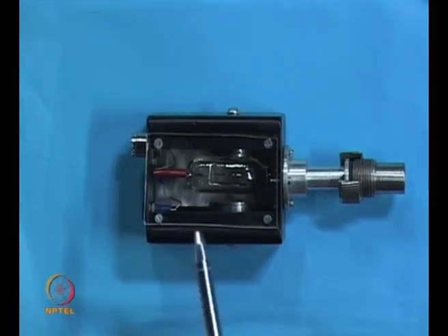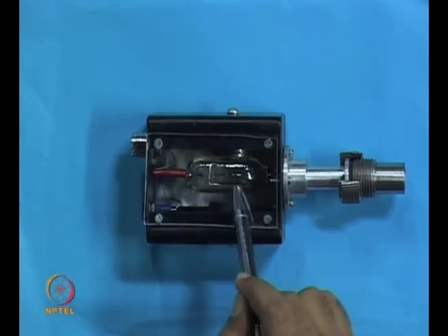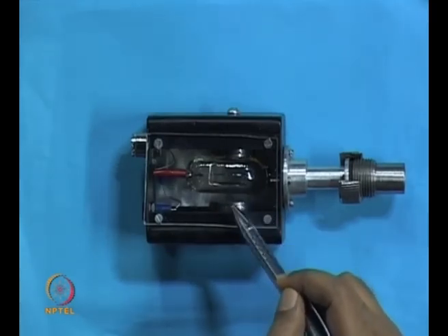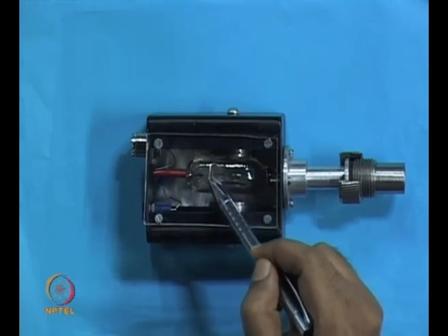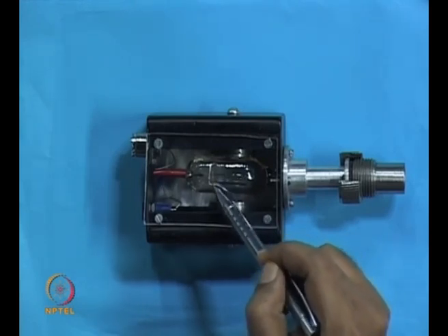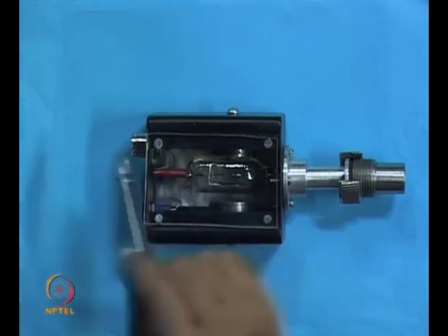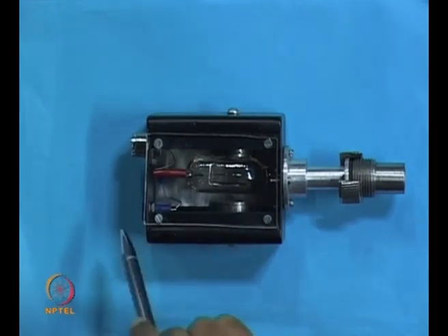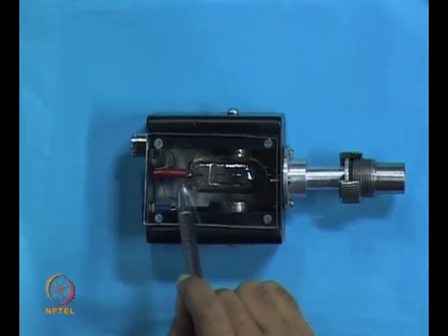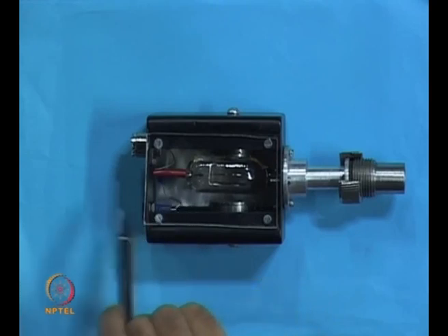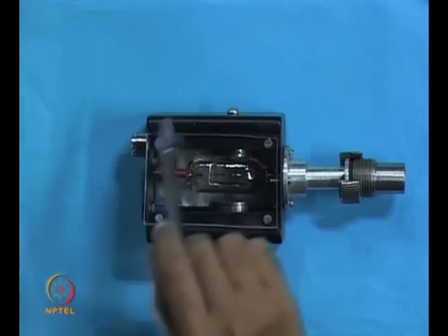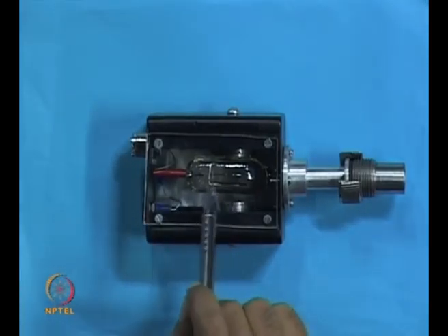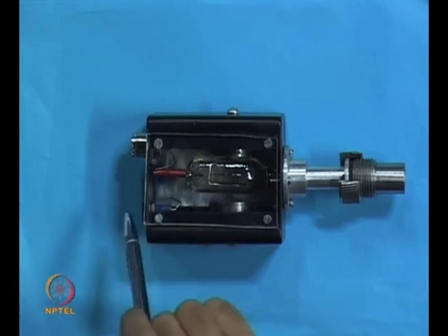Here, if you can see, at the center there is the anode, and on the other sides we have a cathode. I don't know whether you can see, but please try to imagine that you have a cathode on the other side, to which the voltage is given from this side. So the voltage is given over here, while the anode is going to come at the center, and the ionic current is going to be measured from here and connected to the gauge. So this is basically a head, and you can have a gauge where the ionic current which is going to come at the anode is going to be measured.